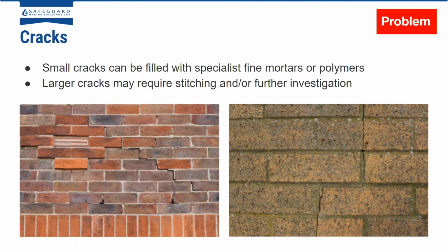So when you have any large cracks or small cracks, these need to be filled with some form of fine mortars or polymers. Large cracks may require crack stitching, or actually a further investigation of why the cracks have appeared, such as any structural movements might need to be investigated.